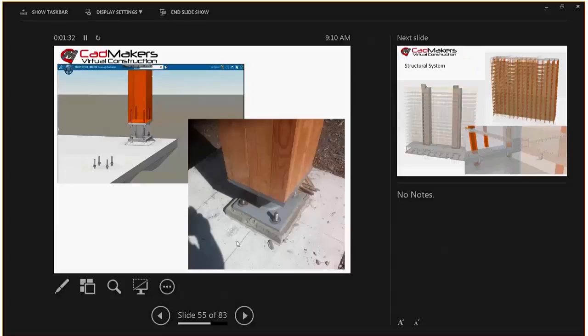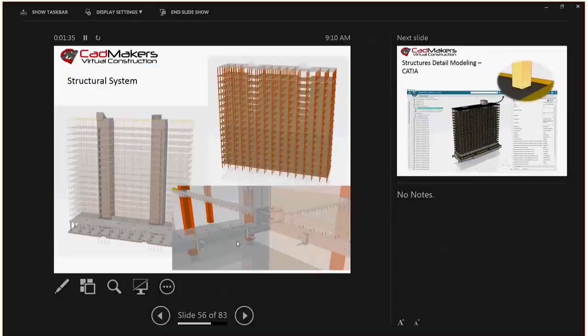Some details from virtual to live. The full building structure, like I said, has 2 concrete cores, cross-laminated timber, and steel connectors. We have every screw, every nut, every bolt, every component in the model. That's not necessarily practical in every project, but in this case, these screws are engineered in Germany and cost about $2 a screw. So it was material to the cost of the project, and it ended up being beneficial down the road from a digital fabrication perspective.